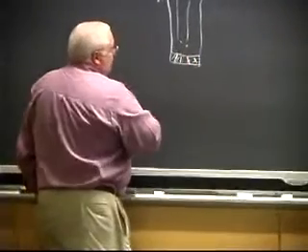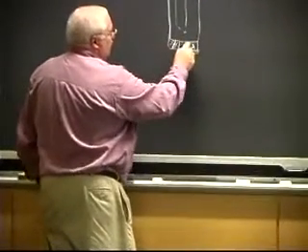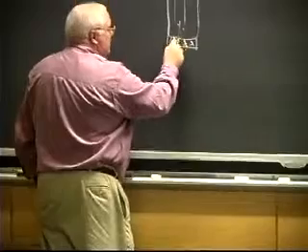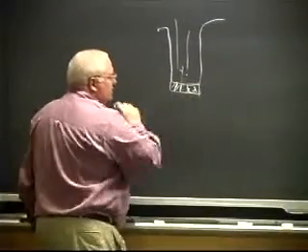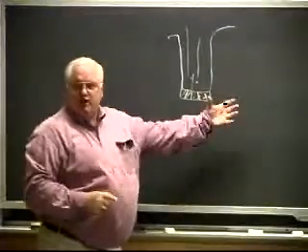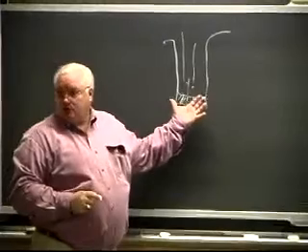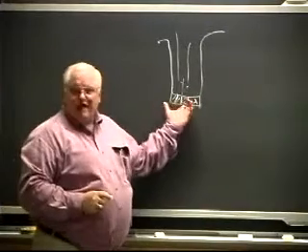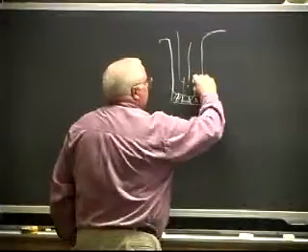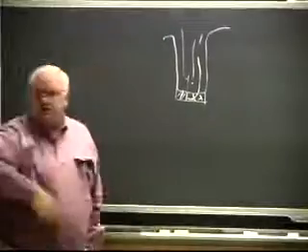Which is one of the reasons they quit using jet burners for drilling rock. But at that type of heat intensity, you're basically expanding this faster than the heat is transferring out to the other sides. Because I have a low thermal conductivity material, I crack it up into little pieces, and the little pieces get blown out with the wind.